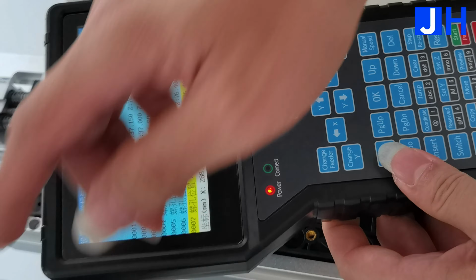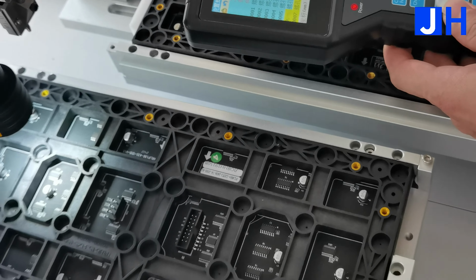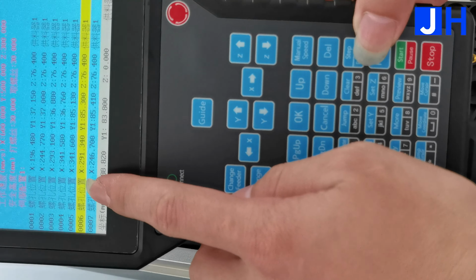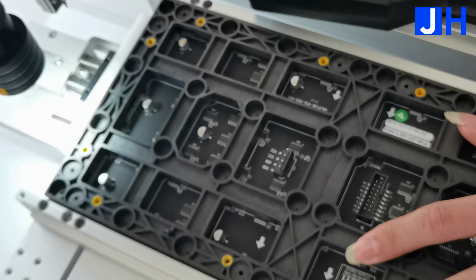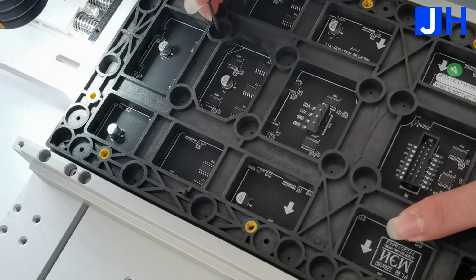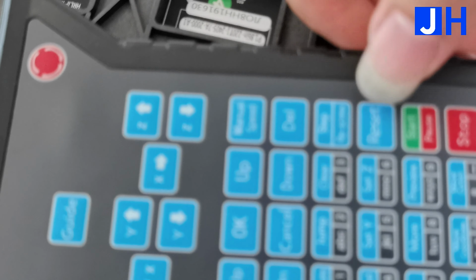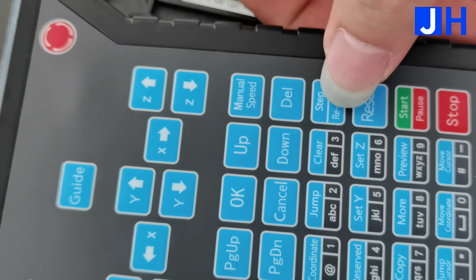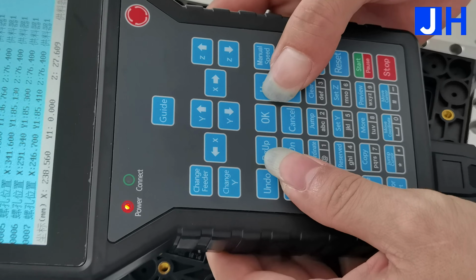Select the coordinates that do not have the screws assembled. Check which screw holes have no assembly screws. Then click single step. After the screw is assembled, tighten the screw manually and check it. The screws are about to be tightened, but a little more torque is required. When we click on the single step, be sure to check whether there are screws at this coordinate.